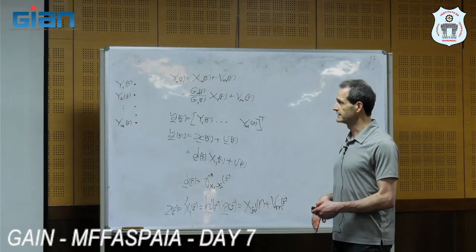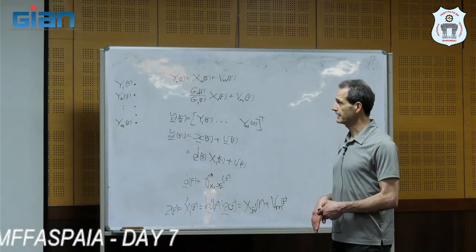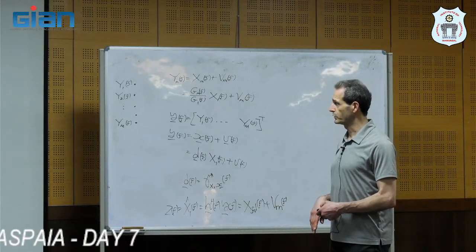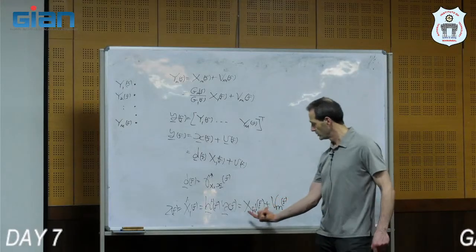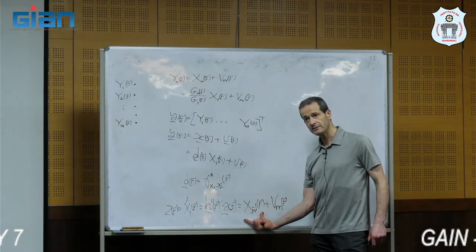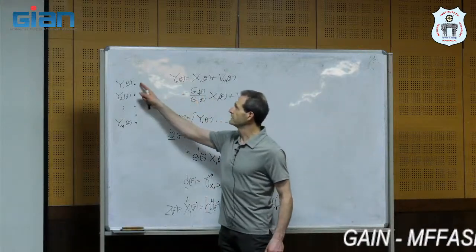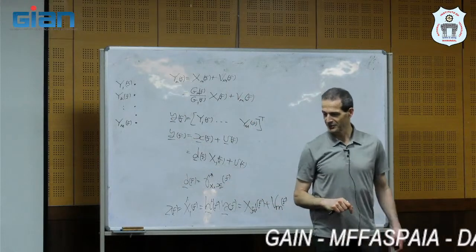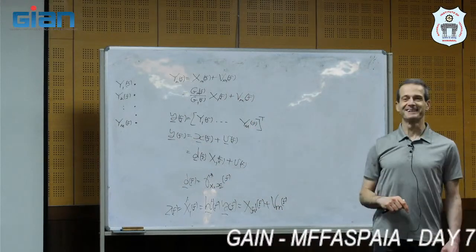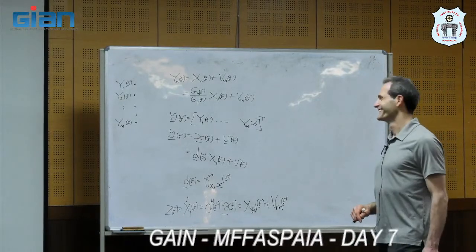And we can define narrowband and broadband versions for each performance measure. And then we can also define the desired signal reduction factor. Narrowband and broadband, it means what is the variance of X filter desired compared to the variance of the desired signal in the reference sensor.